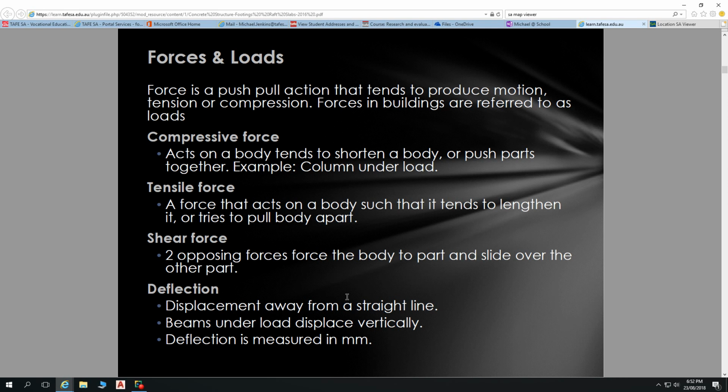But when I put a load on this truss, there is going to be some deflection of the bottom chord. So if the bottom chord is going to be doing this, we have to think about how the trusses interact with our internal wall frames. Inside a building, if we were to use trusses on this building like this, then none of those walls on the inside of the building would be load bearing.